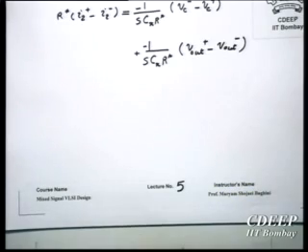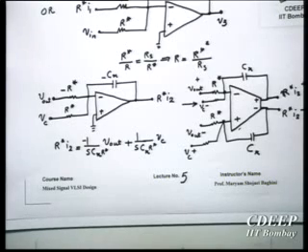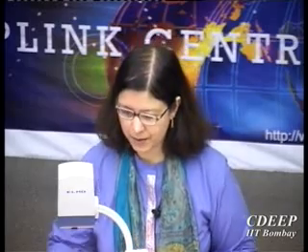So now, at least now you know, if we have a ladder, how to get an active filter out of it. This is called direct simulation. Why it is called direct simulation? Because I am just transferring that LC ladder configuration to an active filter configuration. But the question might be, okay, why not, for example, use a cascade of second order or first order filters, right? This is one of the very common ways of implementing an active filter. So why not use it?